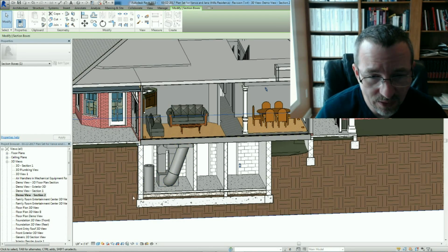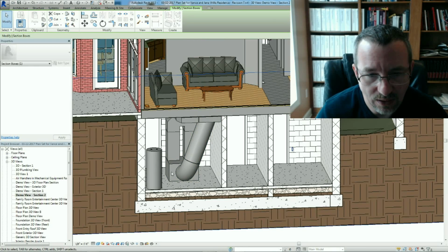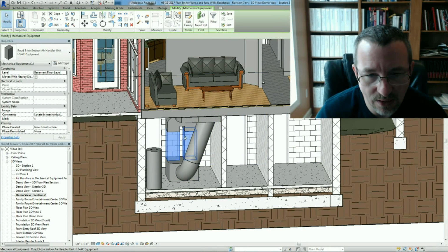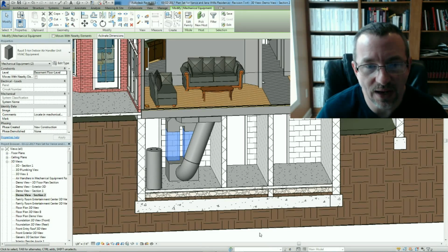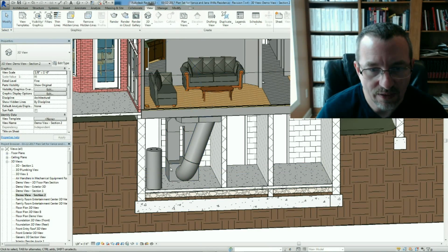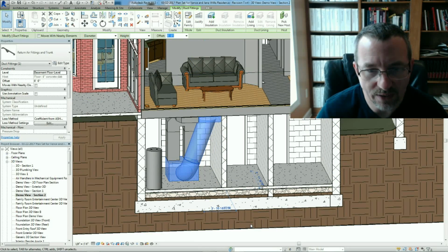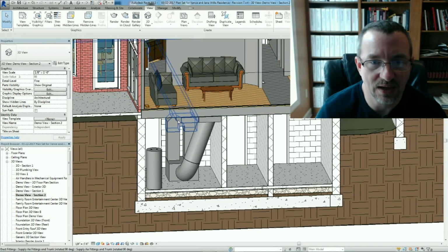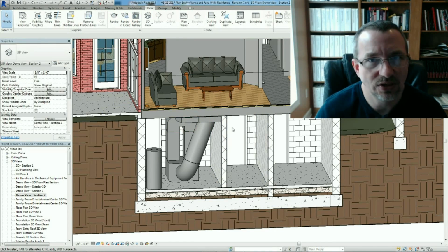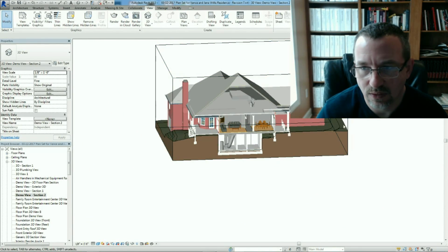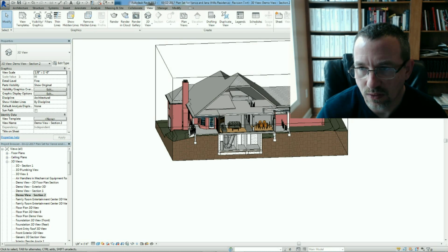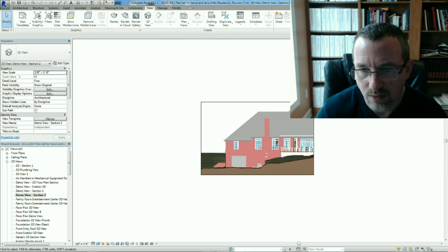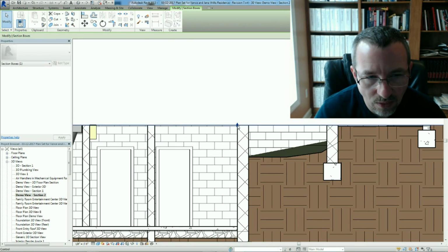So what we're looking at here in this room is this and this. Those two highlighted blue pieces are the air handlers inside the house. And this is the return air duct. This is a 24-inch round piece of duct that comes from the trunk line and goes down into that air box. These are upflow, so air flows up through these things, gets combined, and goes out to the supply vent, which is this thing. Let me show you a different angle.